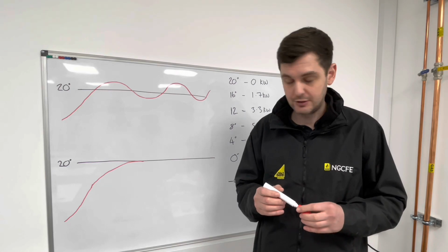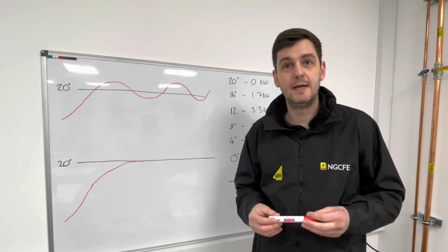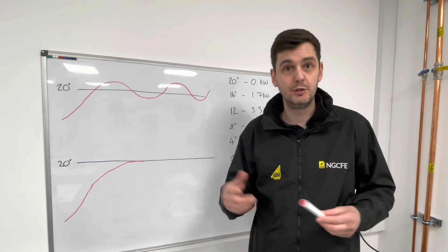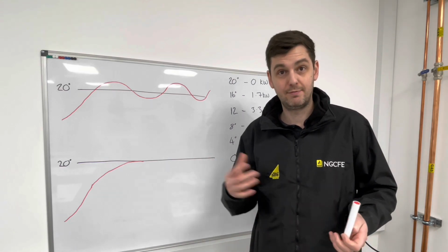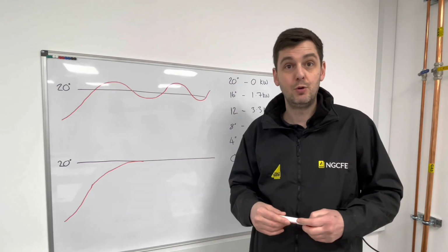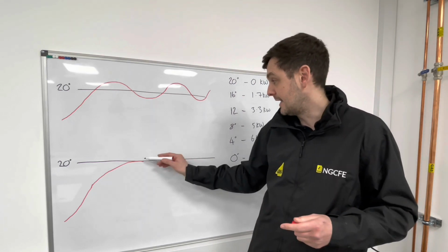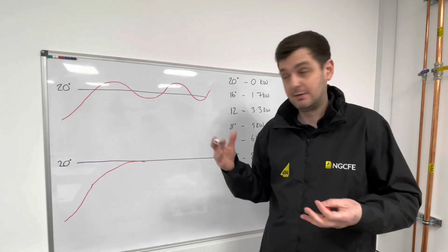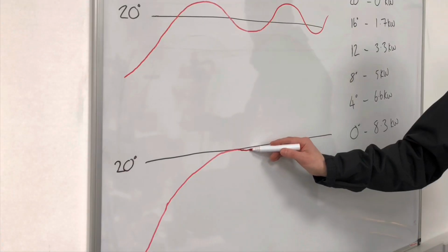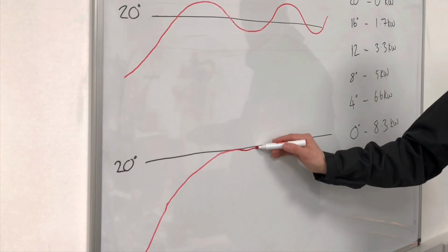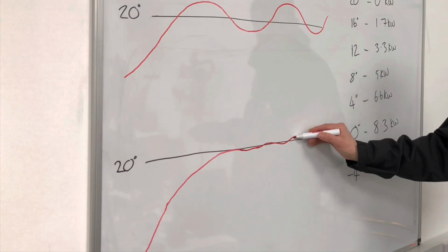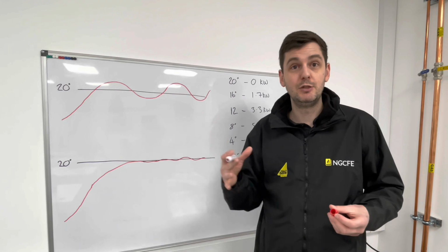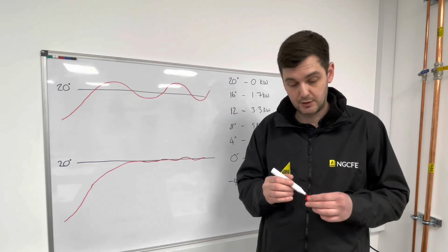Depending on a number of factors, it could be that we've got poor insulation, or it could be that your boiler's minimum modulation output is quite high. You may still get the boiler cutting out, however, it will come back in quicker, it'll react more to the room temperature. So the idea is you might get either smaller cycles, or the boiler will run longer, more continuously on a lower rate, which is more desirable.